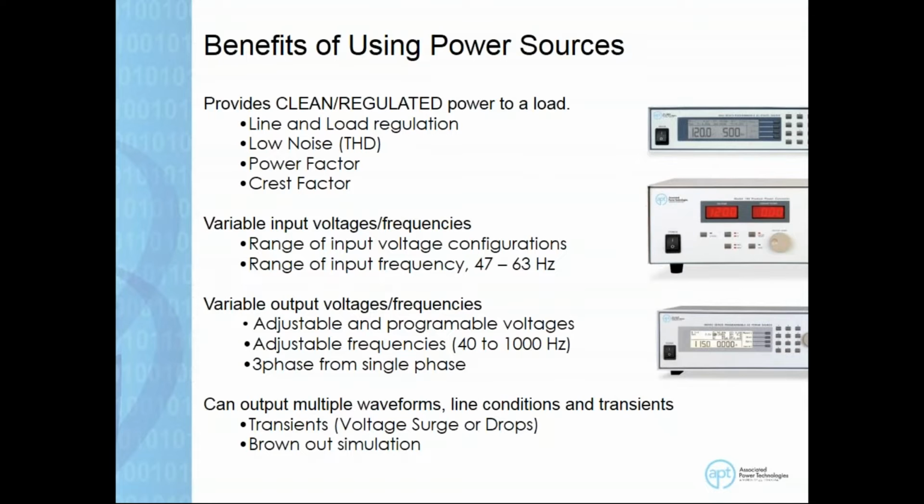Now, when we walk in, we're able to tell them that a power source that could convert frequency is able to take 50 hertz or 60 hertz at the input and deliver 50 hertz on the output. This is where the output frequency and voltage ranges come in. When you're looking at power supplies, you want to make sure that it could output a different frequency than what was available at the input.